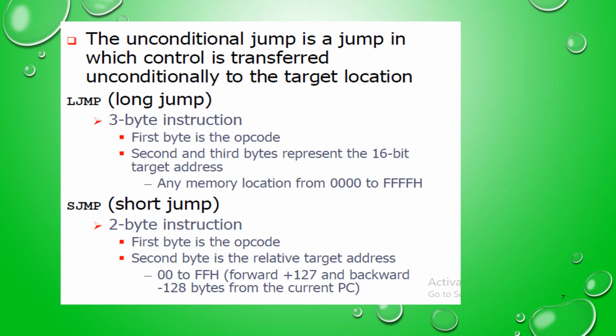One more thing, as far as long jump is considered: though the program counter in the 8051 is 16-bit, giving a ROM address space of 64 kilobytes, not all 8051 family members have that much on-chip program ROM. So this is to be remembered. The original 8051 had only 4 kilobytes of on-chip ROM for program space. Consequently, every byte is very important.